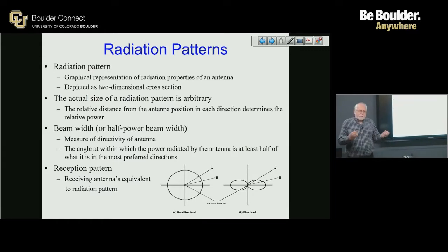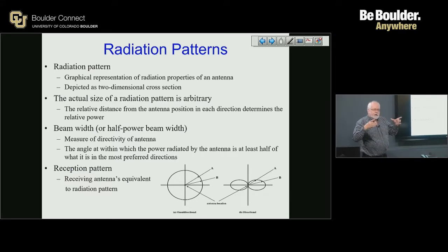There are a couple of different ways to think about this. There are antennas that are omnidirectional in azimuth only, so they have donut-shaped patterns. Basically, they radiate energy out horizontally, but not vertically. You see these a lot in Wi-Fi access points. That's why I bring it up.